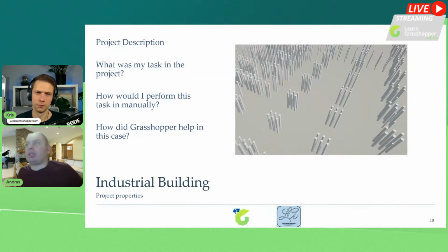The last project was a precast building. After opening the project, I completed the following tasks in the Tekla model: setting up the grid based on the provided data, creating phases, and modeling the piles.